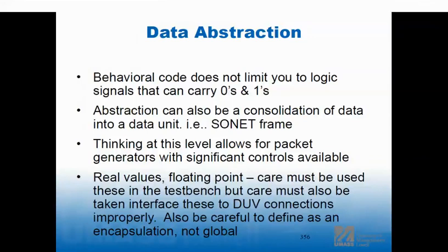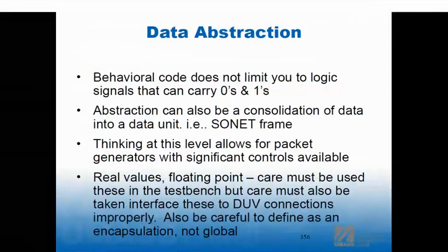So when I said earlier that you could use things like floating point inside the test case, how does that translate when it goes through the bus functional model? Well, you have to fix it. You have to do something with it so you know that the behavioral stuff you did within the test case comes out to be the right signals, the right function on the bus.